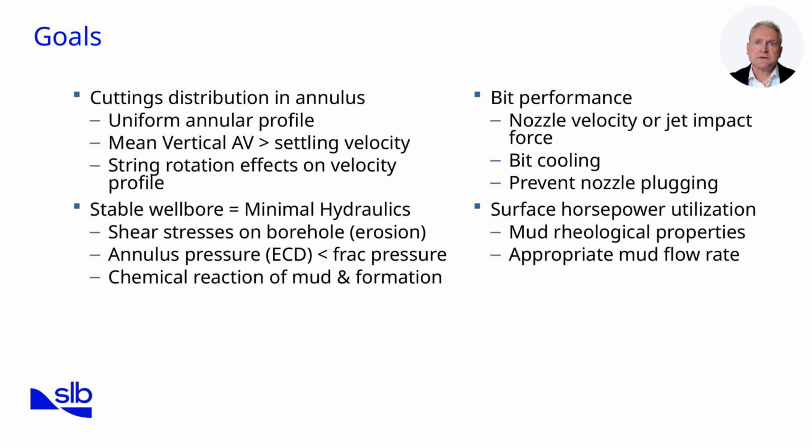Third, bit performance. Clean bottom hole conditions improve penetration rates. In deepwater drilling, where bit trips are expensive, maintaining good jet impact force ensures the bit stays cool and free of balling, extending its life and reducing costly non-productive time. Finally, surface horsepower utilization. The pump's horsepower must be directed toward useful cleaning energy, not wasted in frictional losses. For example, in long ERD wells, efficient use of surface horsepower makes the difference between steady hole cleaning and excessive drag. Together, these goals create a balance between efficient cuttings transport, wellbore stability, and drilling performance.